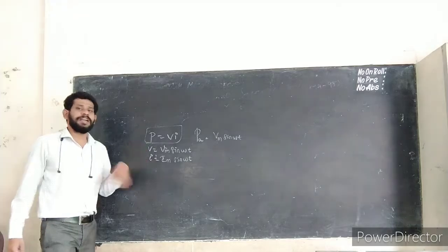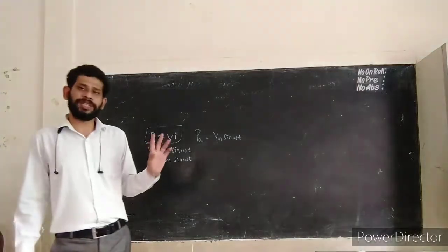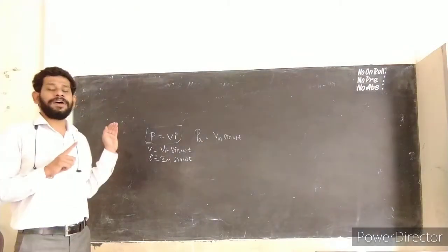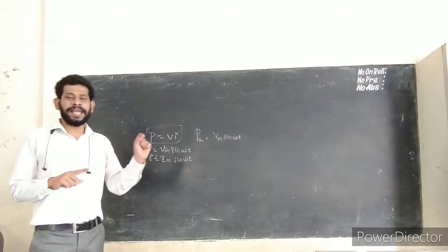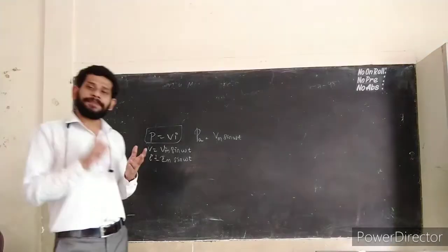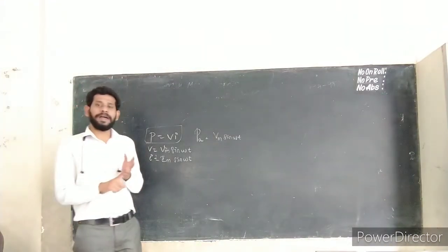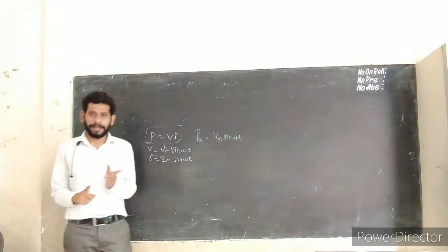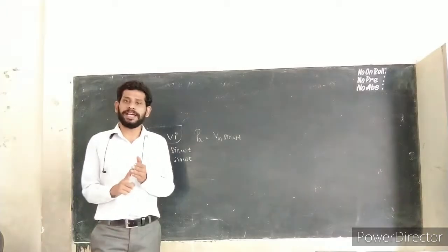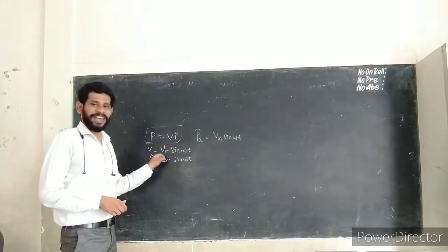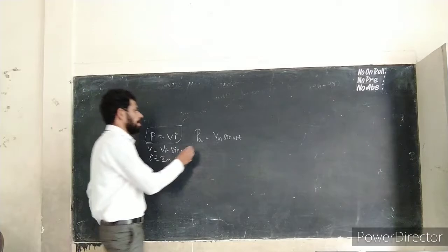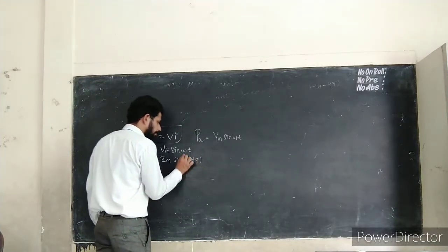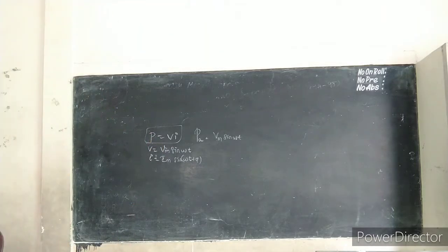The applied voltage is always the same whenever you apply it to the AC circuit. But the current is not the same. For a resistor, I equals Im sin omega t. For an inductor, I equals Im sin omega t minus pi by 2. For a capacitor, I equals Im sin omega t plus pi by 2. So there must be a phase angle difference, plus or minus. So when writing, I equals Im sin omega t plus phi, there must be a phase angle change.